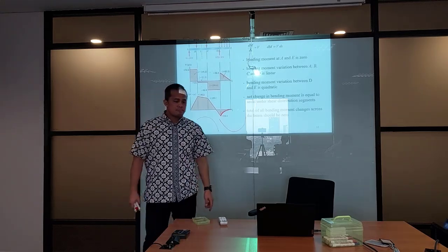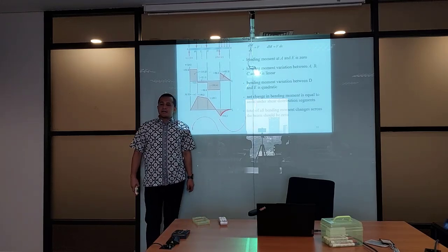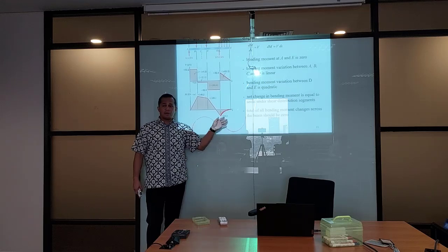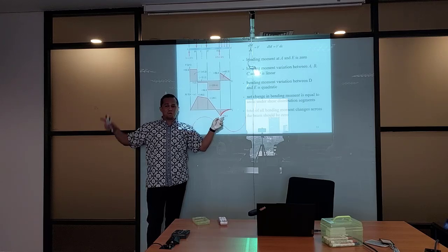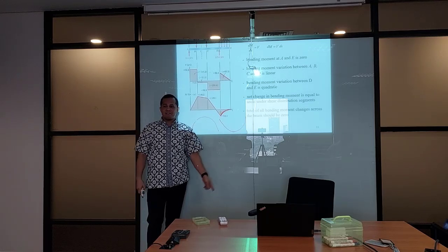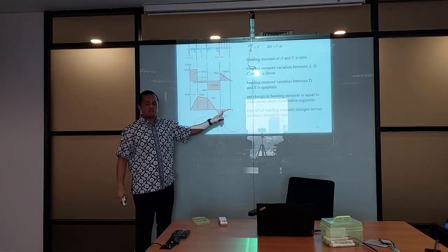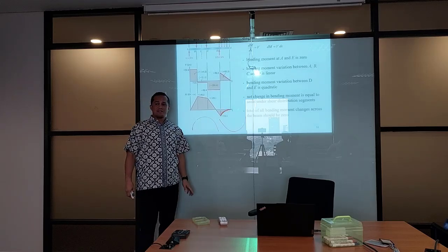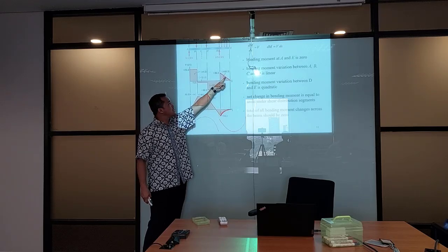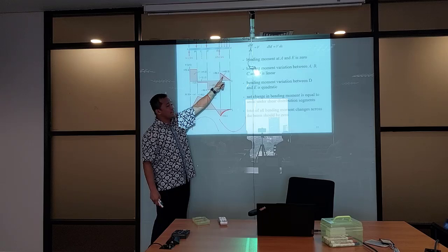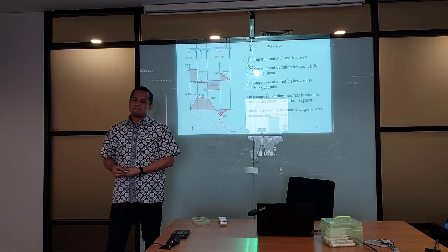If there's a question for you to determine the equation of BMD for every chord, you have the option to do the section I just demonstrated. For example, define the equation of BMD between D and E. Meaning you have to find the equation of this SFD, and you integrate once. But we can do the section from the right.